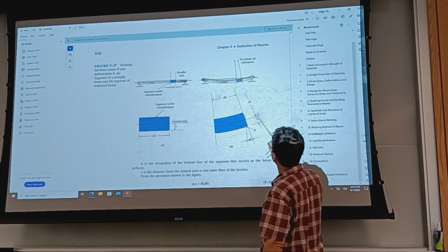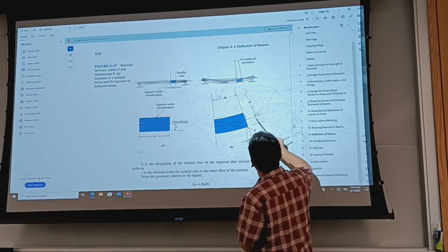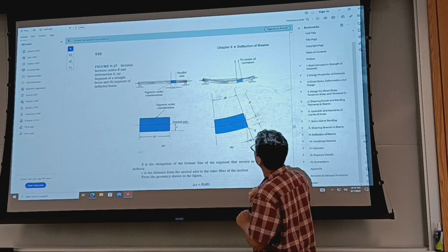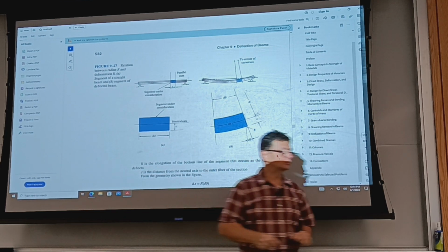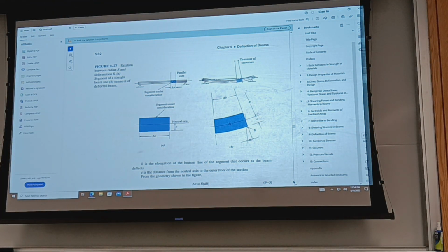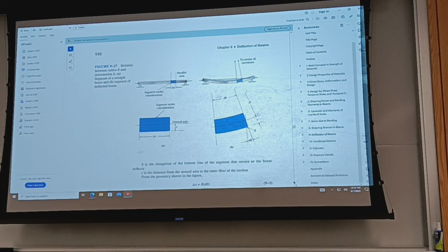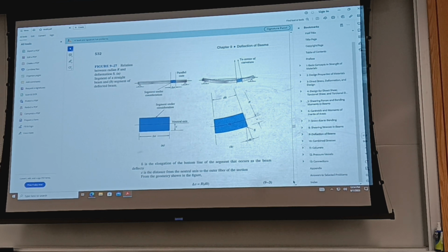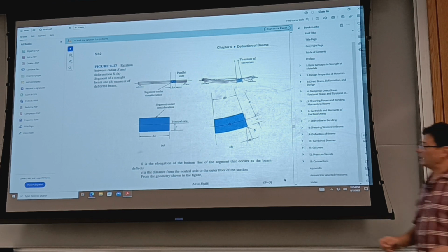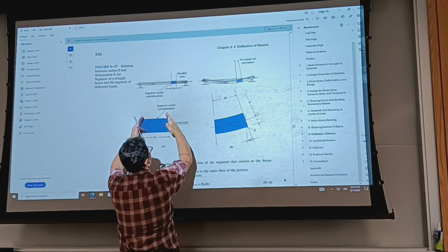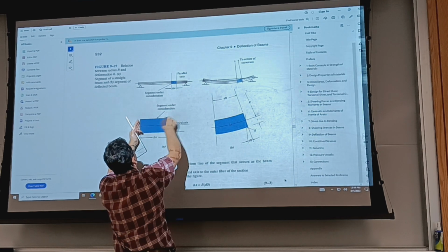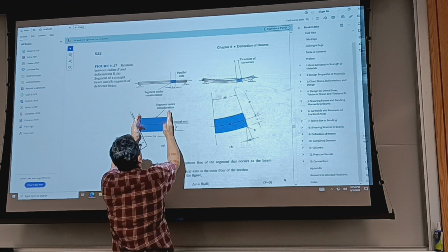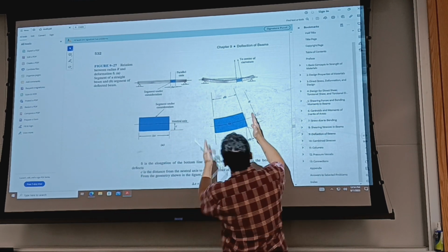The flexure formula will be used, and then we have the radius of curvature. Radius of curvature can be related to y of x, the equation of the neutral axis of the beam, as explained in calculus. Take the piece of the beam as it was originally and rotated, allowing the length of each fiber to remain constant, which doesn't actually happen because of this effect.